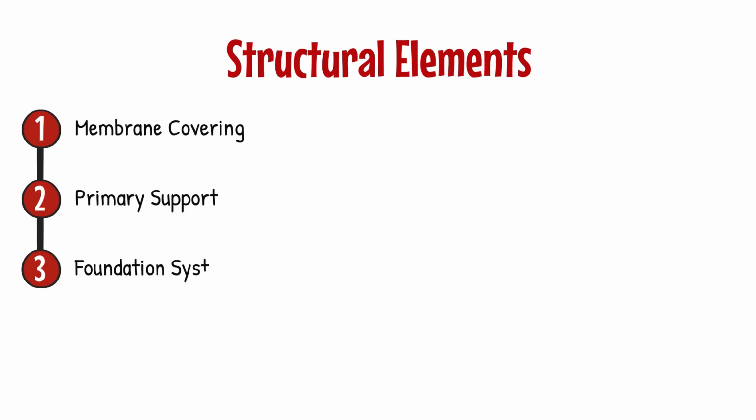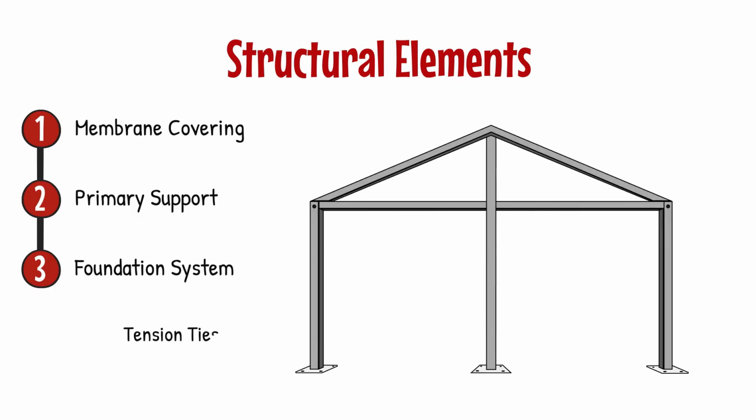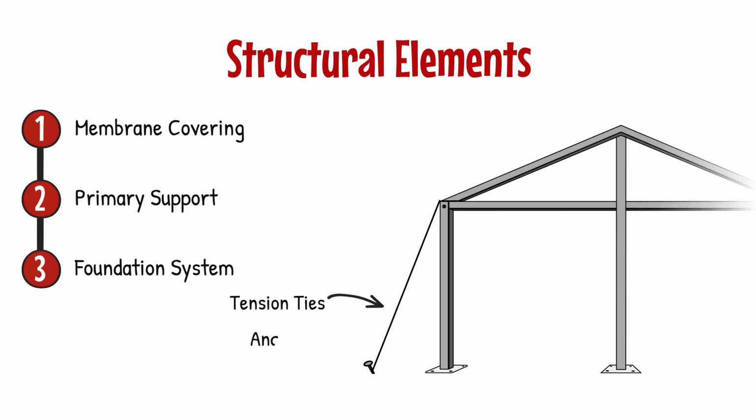Finally, the foundation system. This is comprised of tension ties consisting of cables or straps that maintain structural shape, anchors that create points of resistance against uplift and lateral forces, or ballast systems that provide resistance to overturning and uplift through weights.